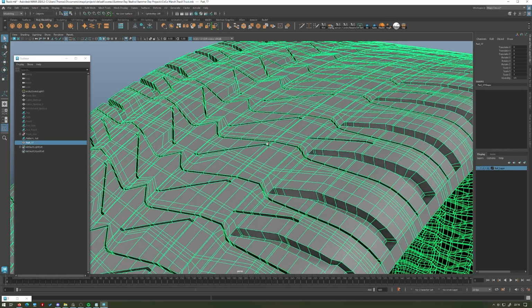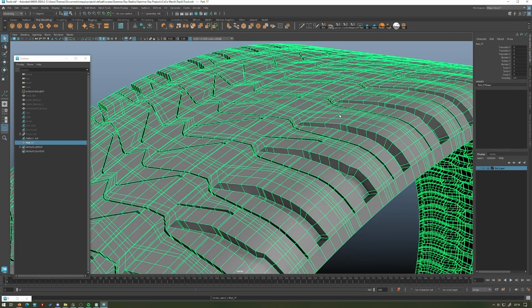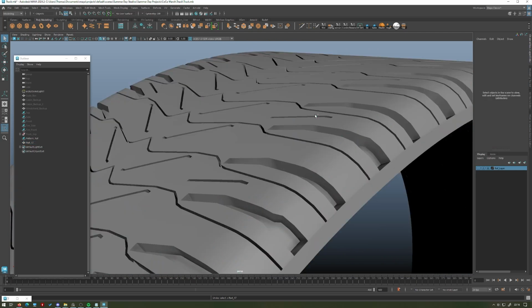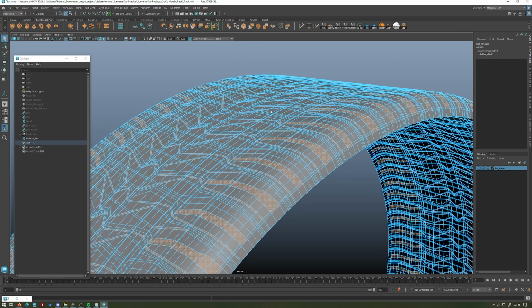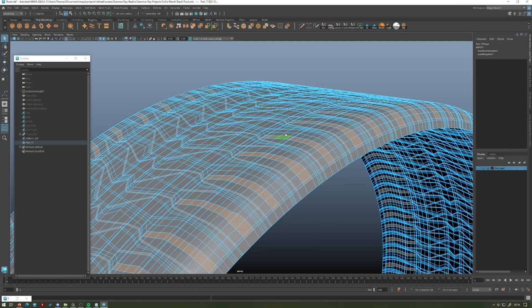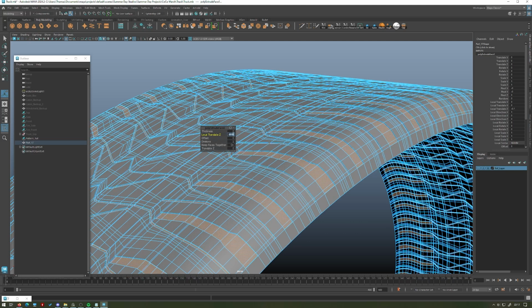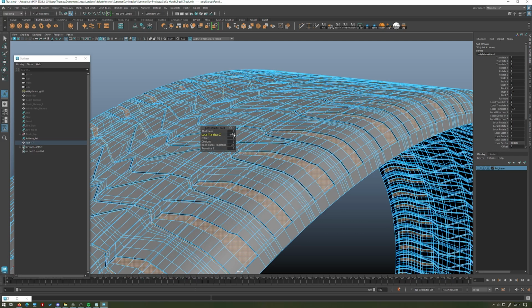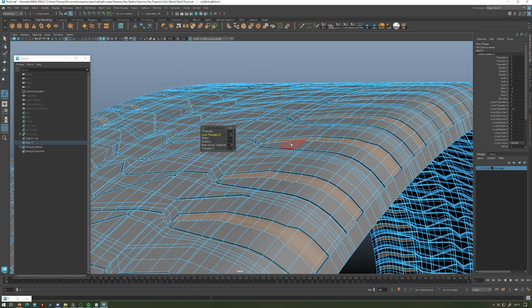And a way to actually do this without having to do a lot manually is if I just undo the extrude that we did. And then we go ahead and redo that. And first of all, before going all the way down, if we just do something like -0.5. Okay, maybe a little bit too much. -0.1. Maybe -0.2. Essentially what I'm trying to do here is create the bevels for us by doing a stepped extrude.